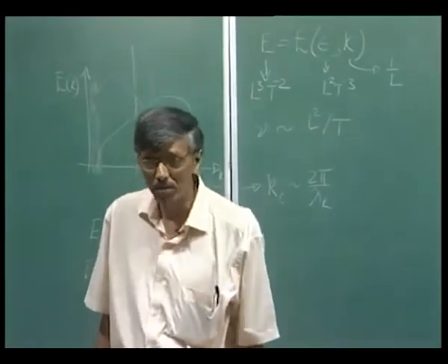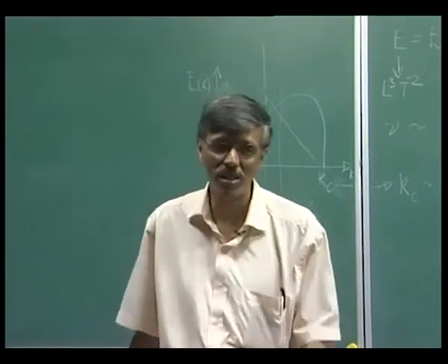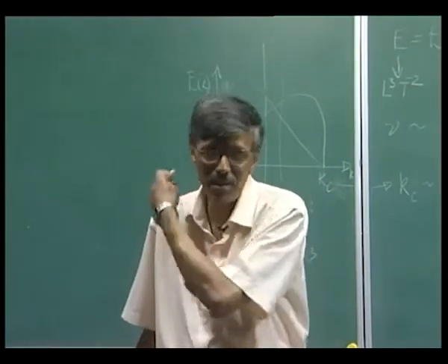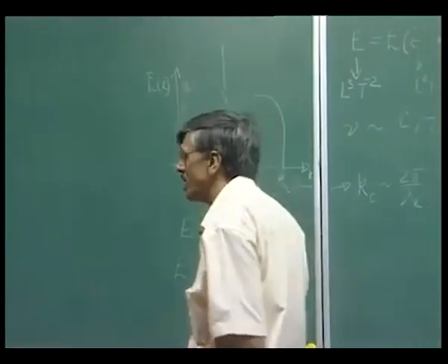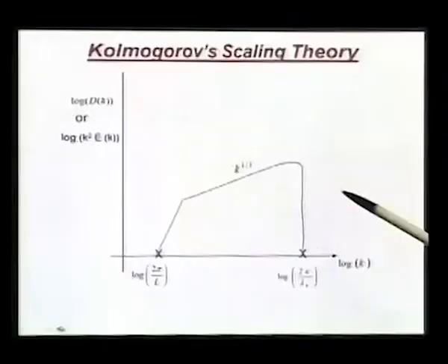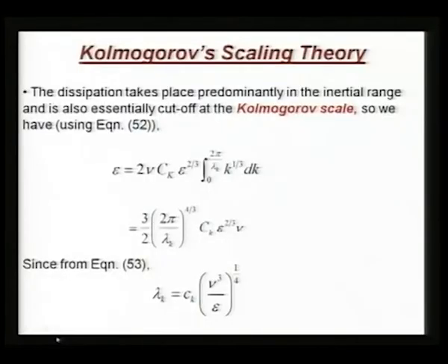So, think of the subgrid scale modeling, it is not a trivial exercise. You will have to model it appropriately so that it mimics that d of k property, right. So, this is something one must do when you generate a subgrid scale model for LES. Make sure that at least in the inertial range it should have this kind of attribute. If it is not, then you have a very poor model. Okay. So, this is your dissipation spectrum, and we can do all kinds of things.